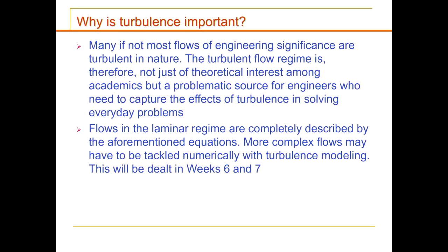Flows in the laminar regime we can even describe from the equations, but more complex flows need to be solved numerically using turbulence models. Today you may encounter a default turbulence model like k-epsilon or whatever. I will talk about it later, as the weeks go by. But just accept for the moment that you are using a good model for your current problem.